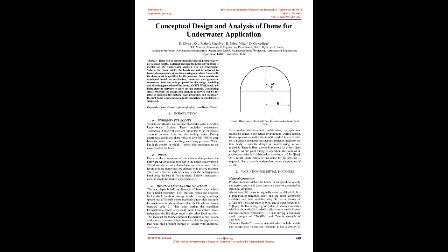Dome models are developed based on mechanism, materials, and geometric constraints. SolidWorks is proposed for the design, modeling and drawing generation of the dome. ANSYS Workbench, the finite element software, is used to carry out the analysis. Considering stress criterion, design and analysis is carried out by changing the material type and properties, and eventually the best dome is suggested. A suitable evaluating methodology is suggested. Keywords: dome, pressure, factor of safety, von Mises stress.